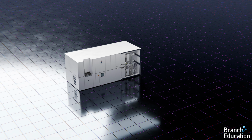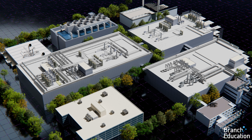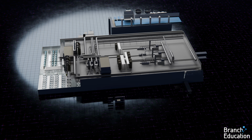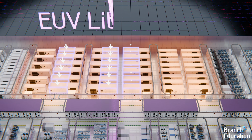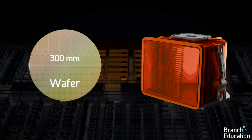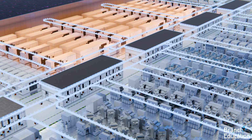Before we open up and explore this EUV system, let's first spend a few minutes discussing microchip manufacturing in semiconductor fabrication plants, or fabs for short, and the exact role of this machine. Inside our example fab are hundreds of machines, of which a couple dozen or so are the EUV lithography machines we've been discussing. To make a microchip, 300mm silicon wafers are stacked inside a front-opening universal pod, or FOUP, and carried from machine to machine using an overhead transport system.